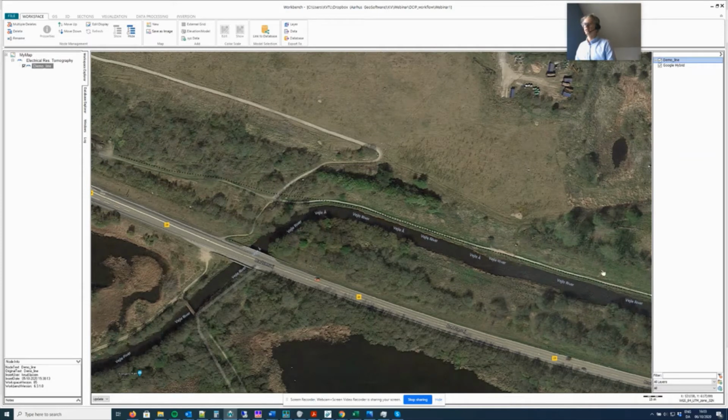And now you can see where your data is actually located out in the real world. It's the black dots here. We can actually change the color of them now, so they are a bit easier to see. You just do that by selecting the layer here, and then you can say edit display. Then you can, for example, make the dots a bit larger, and we can change them to another color, red, for example. So now you can see they are easier to see.